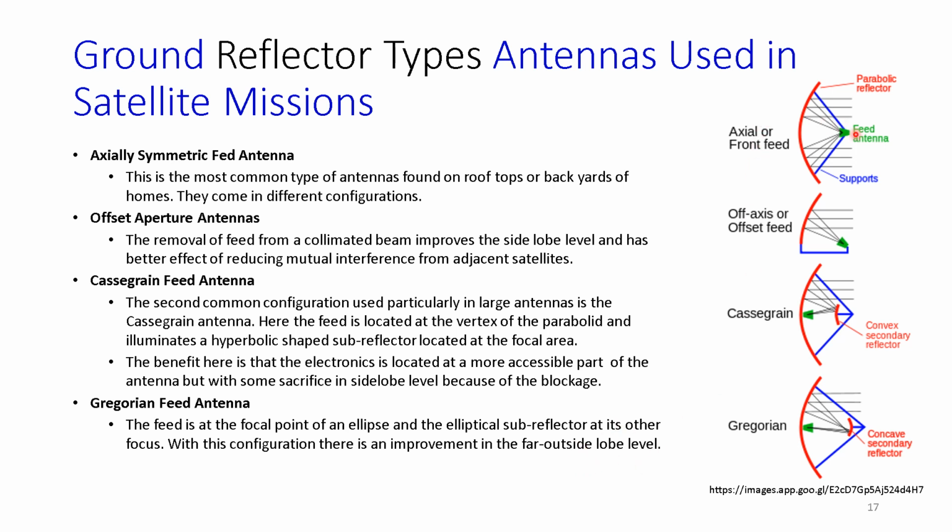So basically we have front feed, and we have feed at the reflectors, almost here. The advantage of doing it this way is that we have access to electronics. Remember that these reflectors could be huge, like 32 meters or so. So if we put the feeder away in the focus, then it will be difficult to maintain. Over here, we can just have access from the back of the dish, and we can go into electronics.